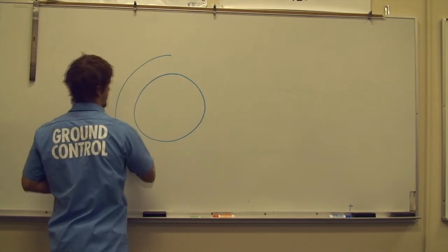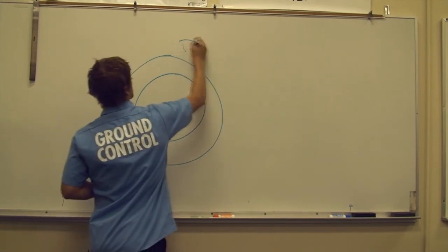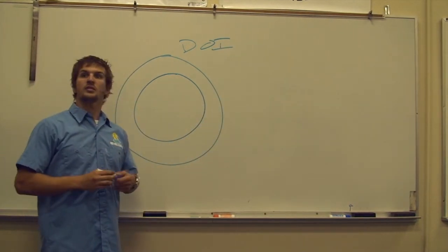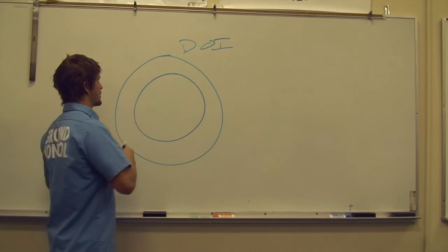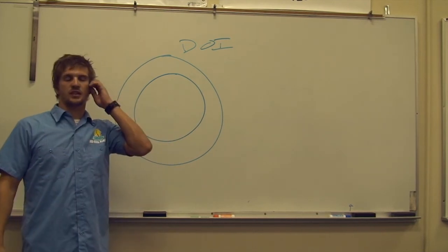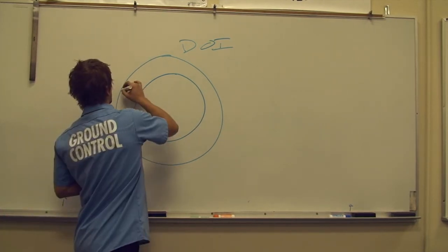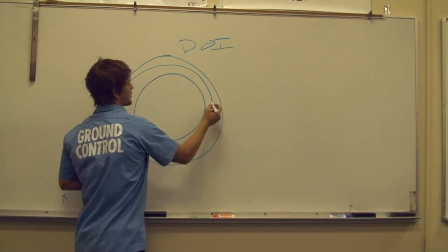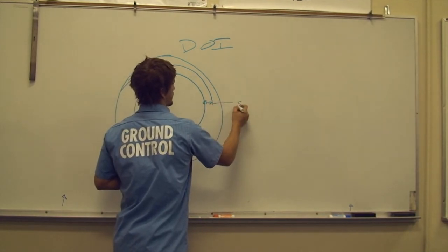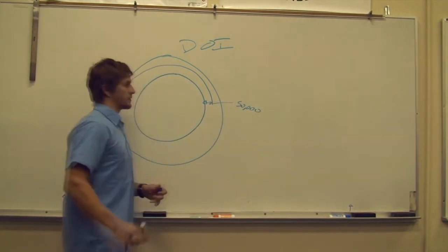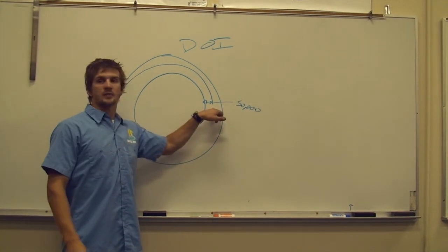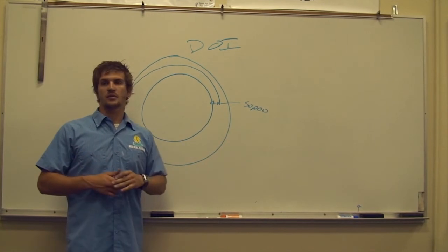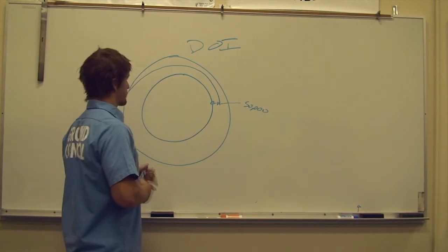And here we are in our parking orbit. As I said earlier, we're going to perform what is called a descent orbit insertion. This is going to bring us down to about 50,000 feet. So we will start to come out of our orbit and begin descending down to the moon. Where we're standing right now is about 50,000 feet. Once we reach this periapsis of the moon, we'll begin a retrograde burn, essentially at about 10% throttle.